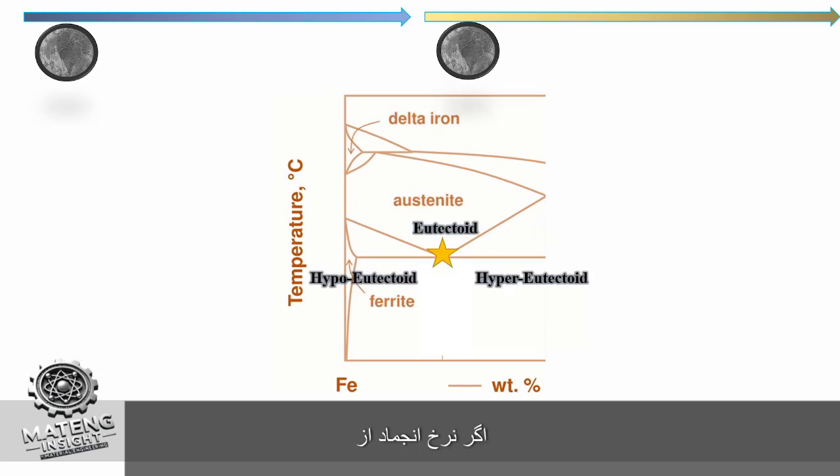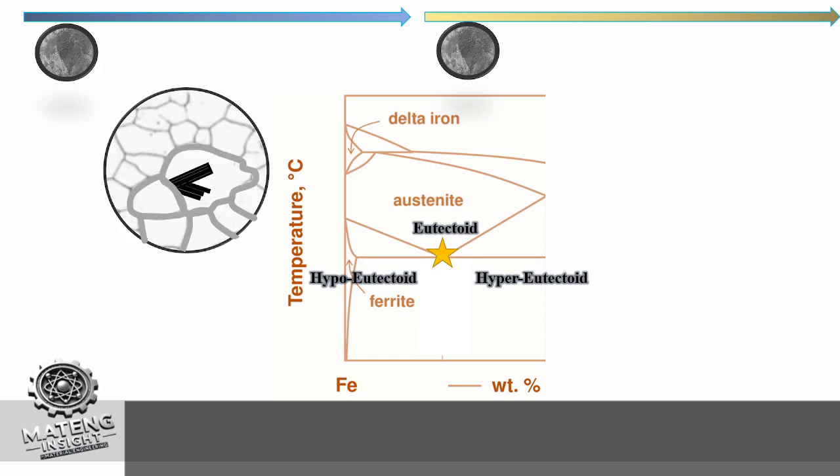If the cooling rate goes out of equilibrium condition, different microstructures will be formed. For example, if the part stays a long time in or above the eutectoid point, or the cooling rate in this range is very low, considering the percentage of carbon, a pre-eutectoid microstructure will form, and the microstructure will change and will not be full pearlite.